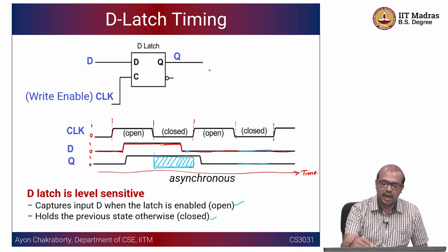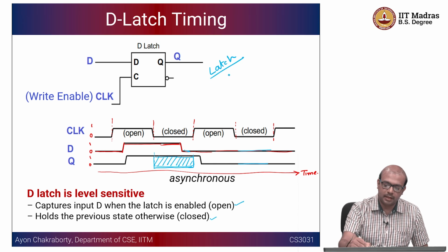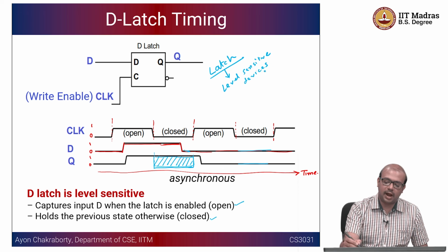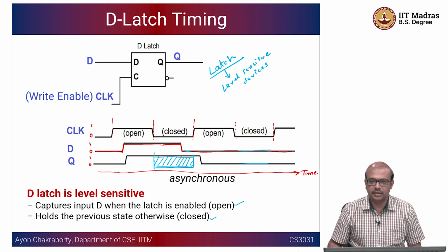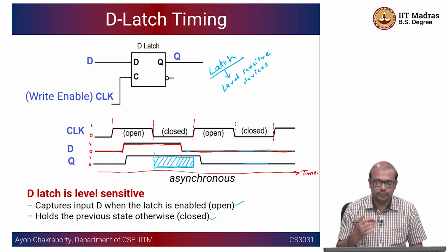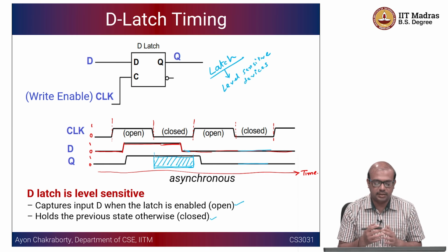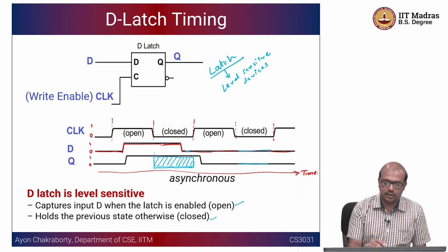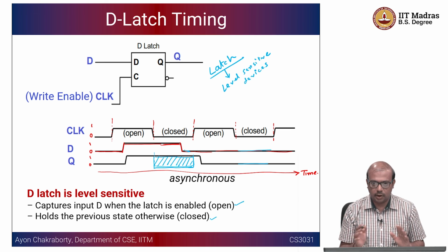Currently all the latches are level sensitive devices, and that has this problem of asynchronous inputs and outputs, because the inputs are not really synchronized with the clock, and the amount of time the clock remains in a high state or a low state could slightly fluctuate in some cases.